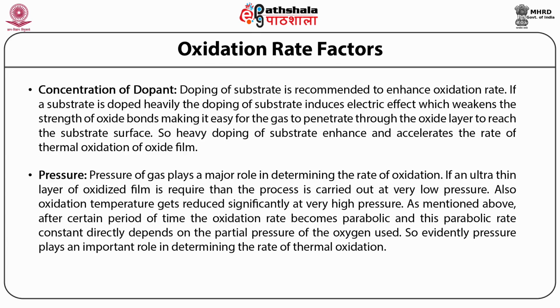As mentioned above, after a certain period of time, the oxidation rate becomes parabolic, and this parabolic rate constant directly depends on the partial pressure of the oxygen used. So evidently, pressure plays an important role in determining the rate of thermal oxidation.